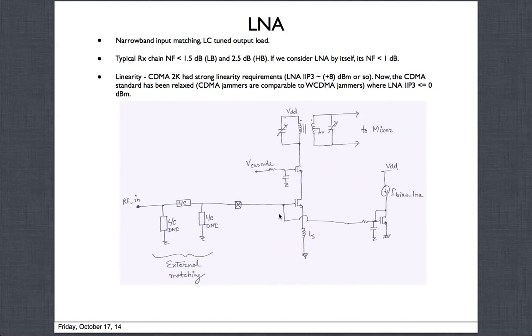That helps you look at 50 ohms and get the impedance matching, and typically in all the theory cases, you can do it with a single element match. But typically why we have this kind of a network is there are lots of other parasitics that come in. There is bond wire inductance, there is inductance on the PCB boards. Some of the traces could be very long, and that's one of the challenges I'll talk about in more detail. So you could have a lot more parasitic inductance, you have capacitance, you have ESD here. ESD is always associated with parasitic capacitance that comes in.